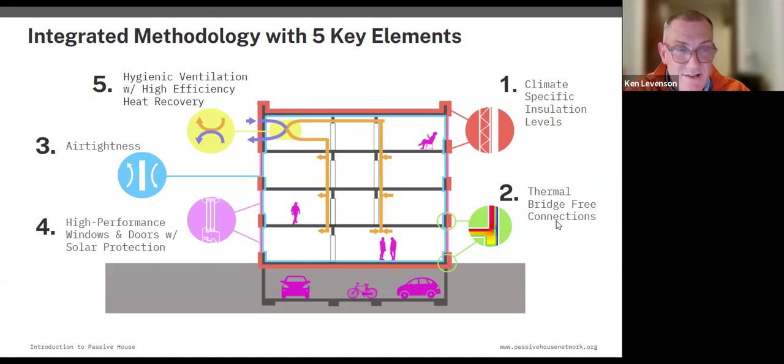It's encouraged actually to have natural ventilation, but we'll get there. The windows and doors are typically going to be a bit beefier, truly thermally broken, often triple pane windows. Think of the windows as providing views, natural ventilation, and passive solar heat gains. But again, we're not creating a greenhouse here. They're also continuations of the insulation and the air tightness. So the thermal quality of the windows is super important.